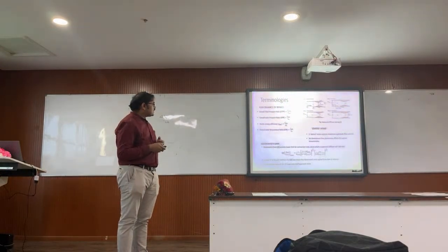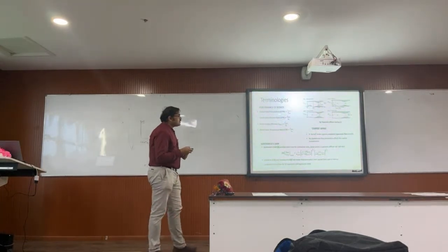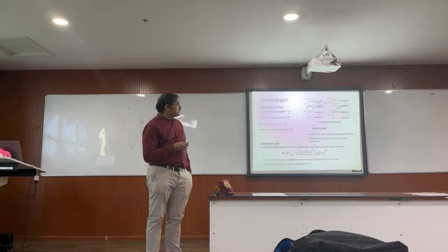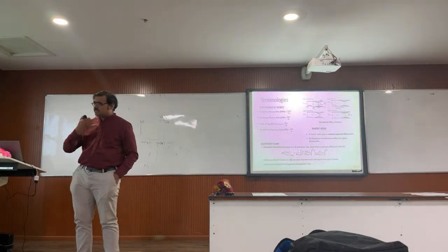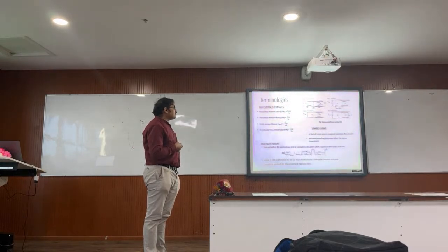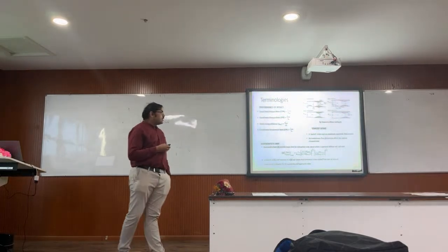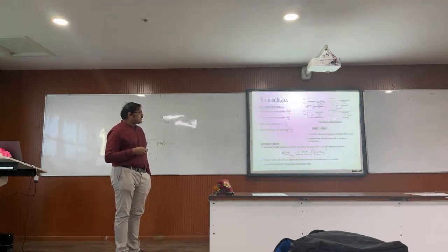So when we look at an intake, since it produces compression, we are interested in the pressure ratio. And not only that, we are also interested in what is called the total pressure, because the total pressure ratio actually tells how much entropy is getting generated. The more the entropy gets generated, the more the efficiency starts decreasing. So we would like to have as high a total pressure ratio as possible. And static temperature is also important because the combustor eventually requires a certain static temperature to be provided. So these are various performance parameters of an intake.